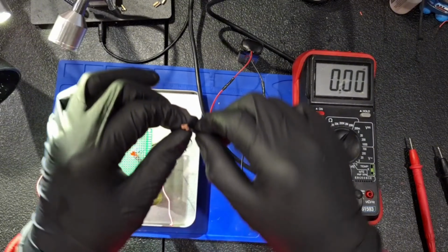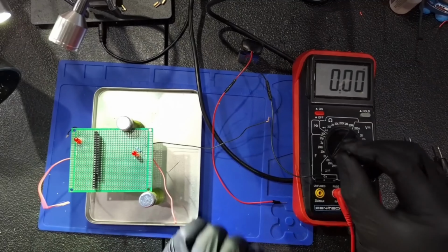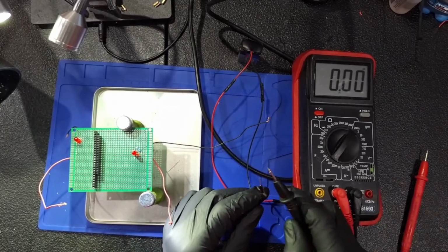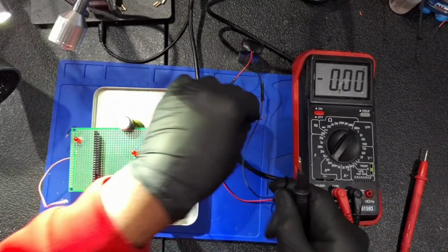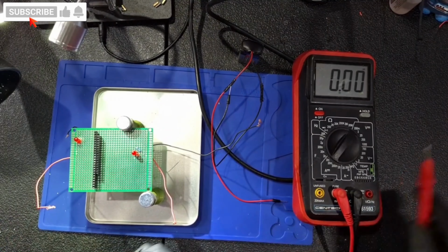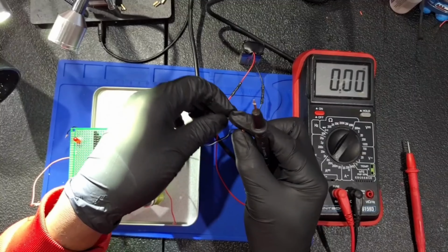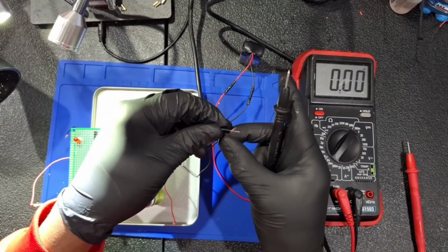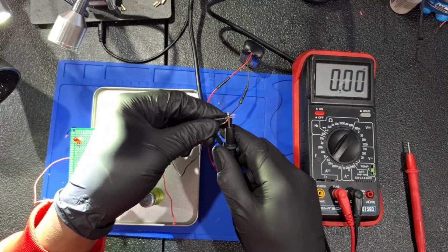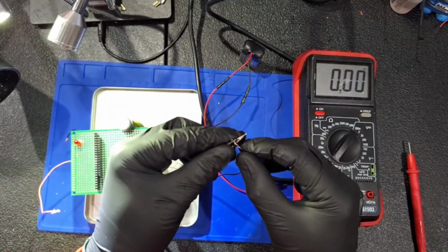Alright, so the problem I was having: I understand that the red connection from the positive on the battery will connect to the red probe on the multimeter, right? But the black connection to the black wire on the LED, when I was thinking about breaking the circuit, I was breaking both sides. I was removing the connection on the black wires and also the red wires. So when I removed the red wire from the positive on the battery and connected that to the red probe, I then did the same thing from the black side. I was saying, all right, I have too many wires now, where should these go? So it was a bit confusing how to set up the multimeter so that the current runs through it. And this is probably a common mistake that beginners make.